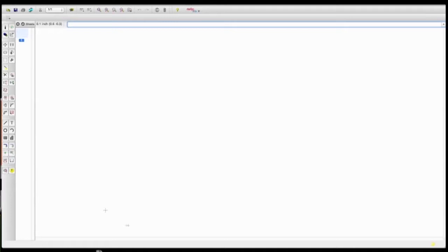And I want you to notice one thing right here. This little plus or crosshair right here is the bottom left side of your drawing. You don't have to follow that, but you're going to want to follow that, mainly because you make it a habit. Because when you get into designing the PC board side, it's very important that you use this, because that's where your PC board size starts and goes this way and goes this way.